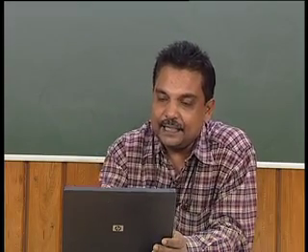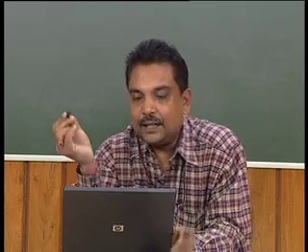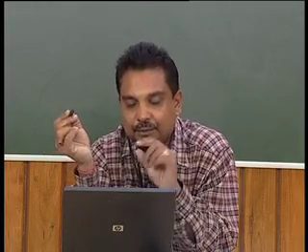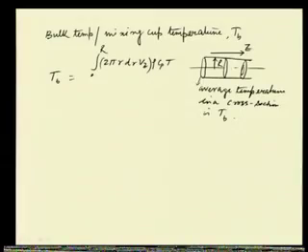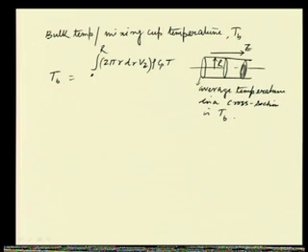If I consider any cross sectional region, and take a smaller element 2 pi r dr, then 2 pi r dr into V z, where V z is the velocity at that particular point, becomes the volumetric flow rate. Into rho, it becomes the mass flow rate, into C p the heat capacity flow rate, into the temperature, which becomes the total energy flow, m C p delta T, with T reference taken as 0.